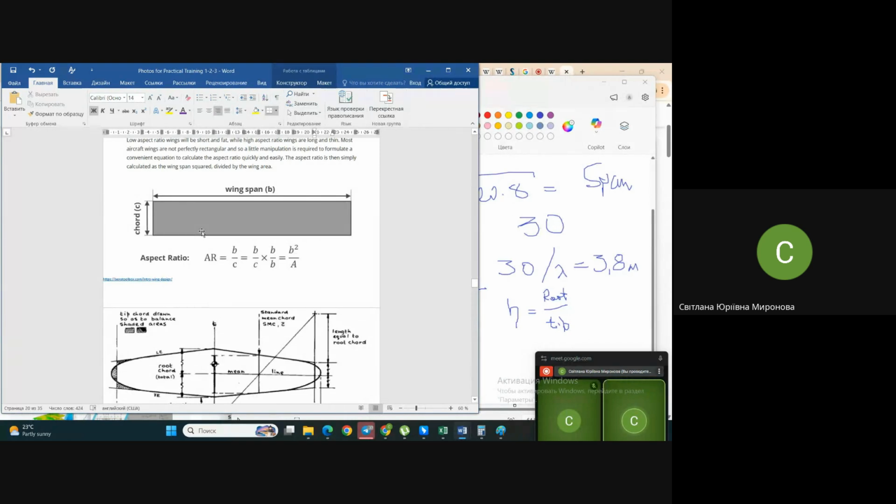You do remember the obsessive ideas of different groups of designers. Those responsible for the airframe are obsessed with minimum weight, minimum mass. Those responsible for aerodynamical performance, the aerodynamical group, are obsessed with minimum drag. So your considerations, whatever they are, should be subordinated to the idea of minimum drag.